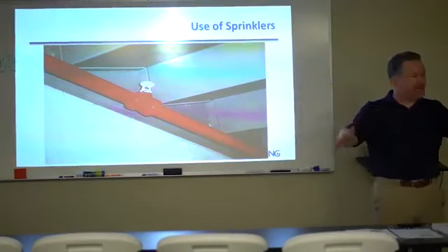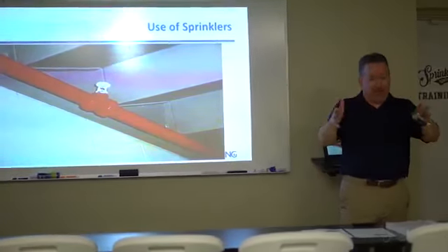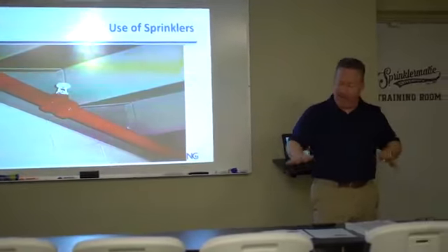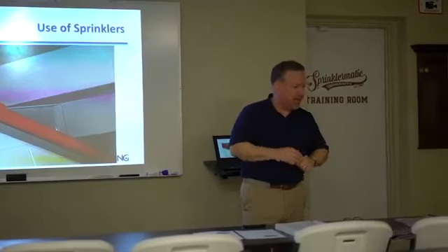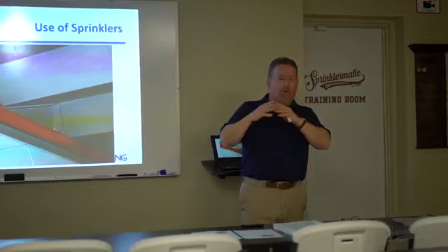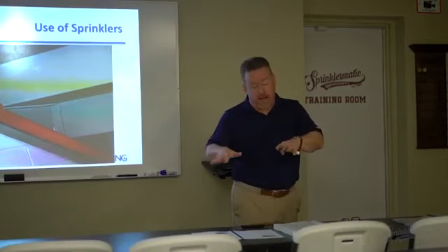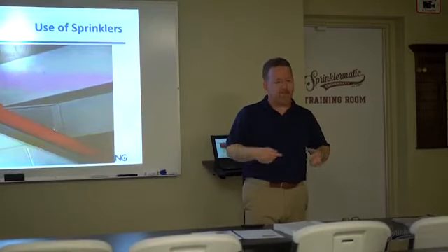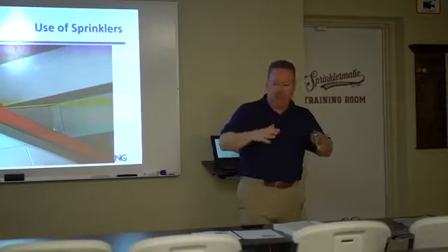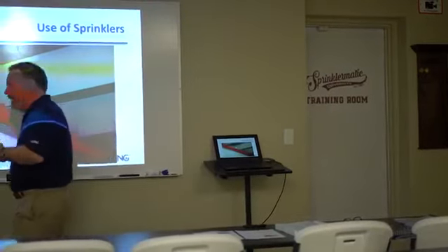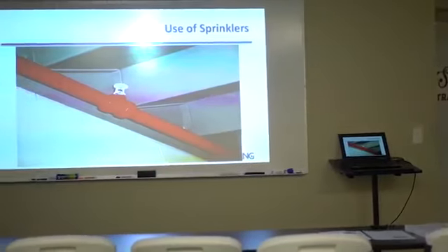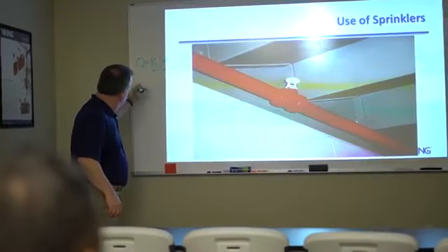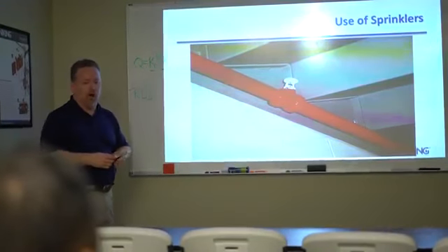The amount of water is based on what's underneath it. All right, so I've got all these tables in here and they burn at a certain rate. If we set them on fire, they get going and they burn at a certain rate, which requires a certain amount of water to put them out or control the fire. That's called the required delivered density. So over the years, fire labs have burned certain things that are representative of this space. And that's the RDD, the required delivered density of water.